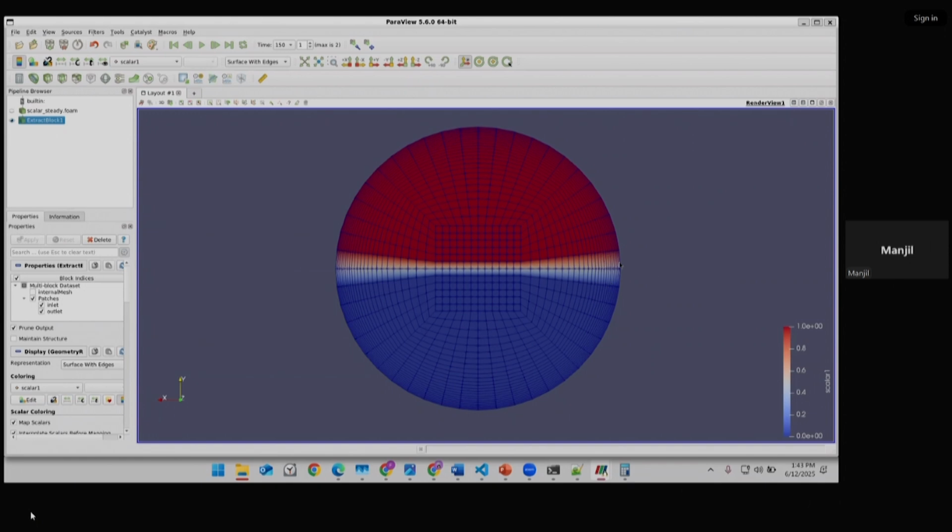If you have a more coarse mesh, you can see that near the arc the mesh is more coarse, and the band is again greater. In the center part, the mesh is less coarse than at the outer part, so the band is quite smaller. So this is an artifact of coarser mesh and numerical schemes. This is numerical diffusion. So now this is the case.